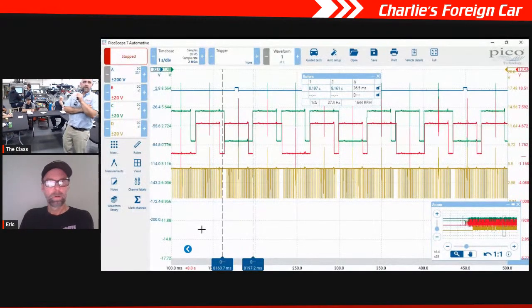Well, Felipe is still looking at that stuff. So then we tested the signal going to each VVT solenoid. Yeah. And when it grounded out, the one on the exhaust cam, the one that does not move, both wires were at B+, and then the one wire grounded out. It went down to about 0.5 volt, and we got nothing, no RPM change. That's the one that does not move.